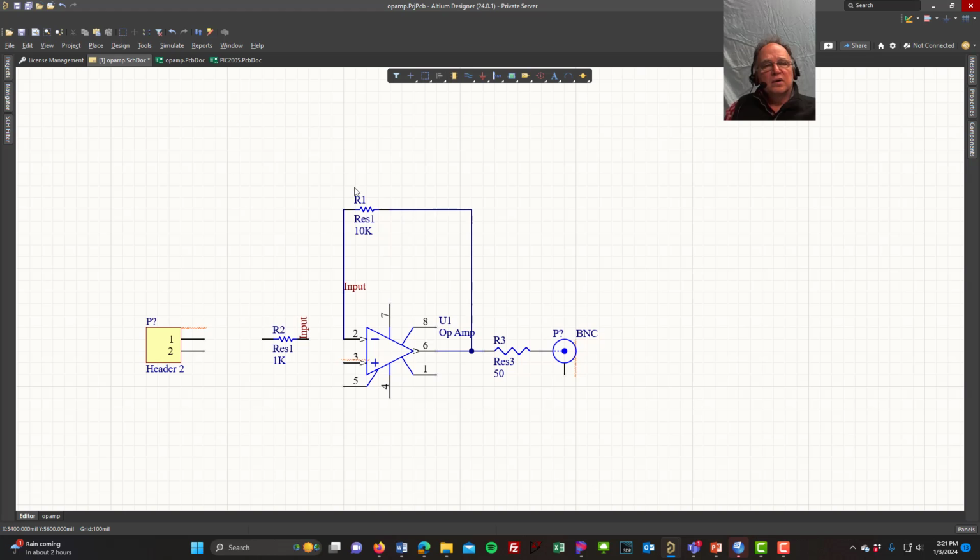Well, let's look at our functions now. I'm going to take this input here and delete it. I'm going to take this input, and I did Control X. Control X cuts it and it's gone, but it's still in my paste. And then I'm going to paste it. Now I'm going to put it over here. There's input. I'm going to highlight that guy, copy him, and paste him here. And I'm going to wire this straight across. Makes a little more sense to have this say the input than this function.